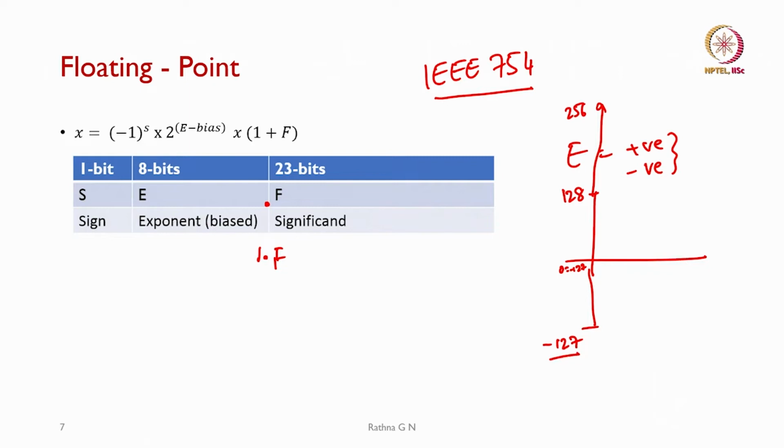And we went on to discuss some of the problems, both in fixed point multiplication and addition, and in floating point addition and multiplication, and how we have considered them. For most architectures, as we know, multiplication means multiplying the fractional bits in floating point and adding the exponents to get the result. Whereas for addition, if you are adding two numbers, then you have to bring them to the same exponent and then add them up.